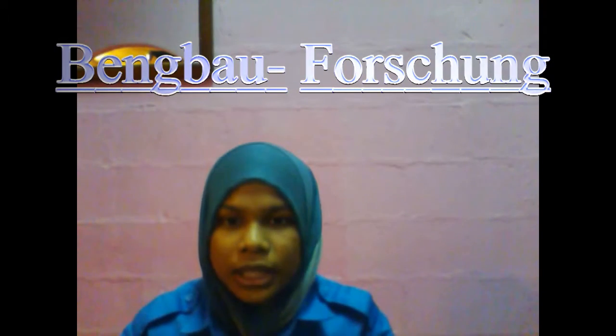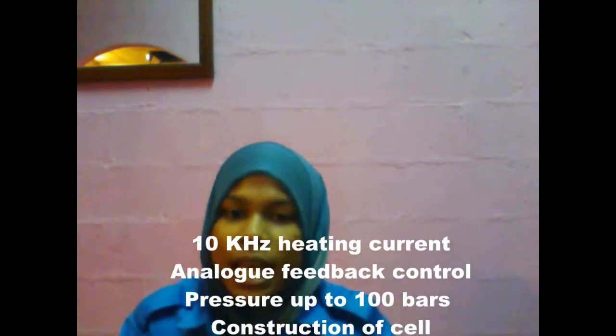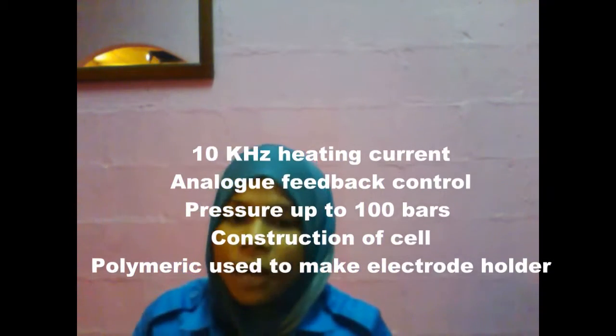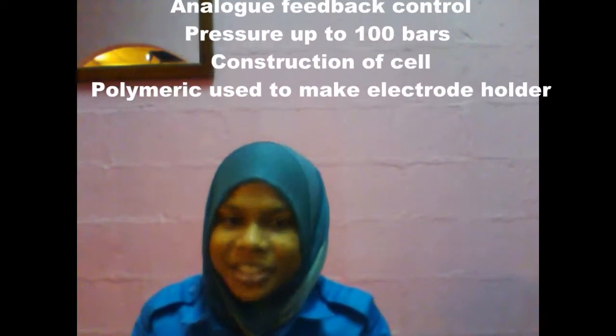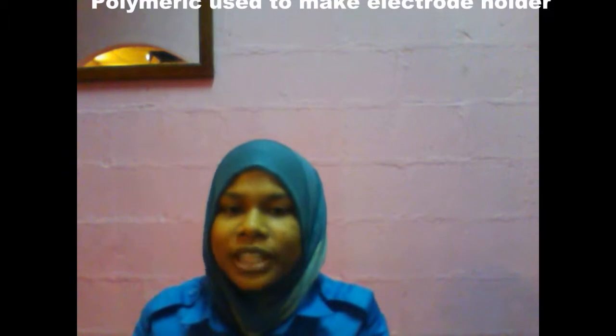Coal sample was placed between layers of a folded mesh to absorb resistive heat. Next, the evolution continued at Brunel with a 10 kHz heating current used, an analog feedback controller, and pyrolysis and hydropyrolysis carried out at pressures up to 100 bars. Besides, the electrode holders were made of a cell polymer. Okay, so now the wire mesh reactors are commercially acquired from Brunel.